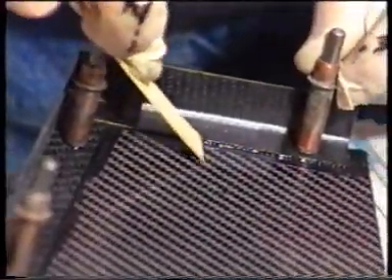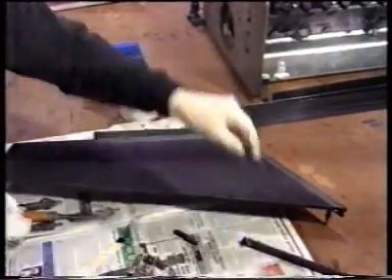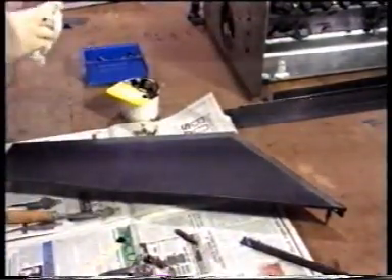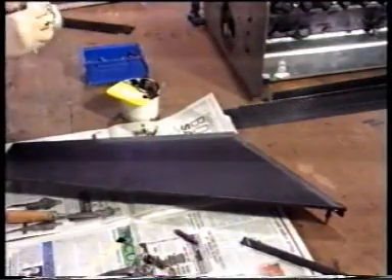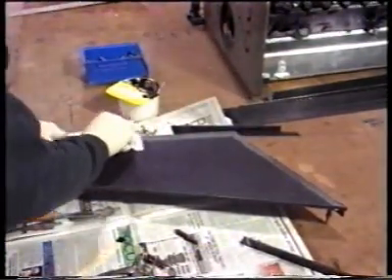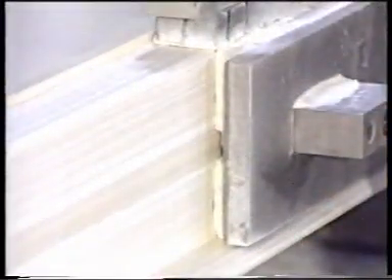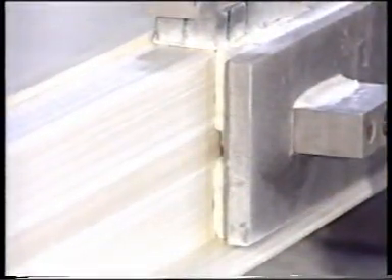Adhesive bonding forms permanent joints. Surface cleanliness is critical for optimum adhesive bonding performance. All grease, mold release, and other contaminants must be removed from the contact surfaces or joint region before adhesive application. Abrading the region first is better still.